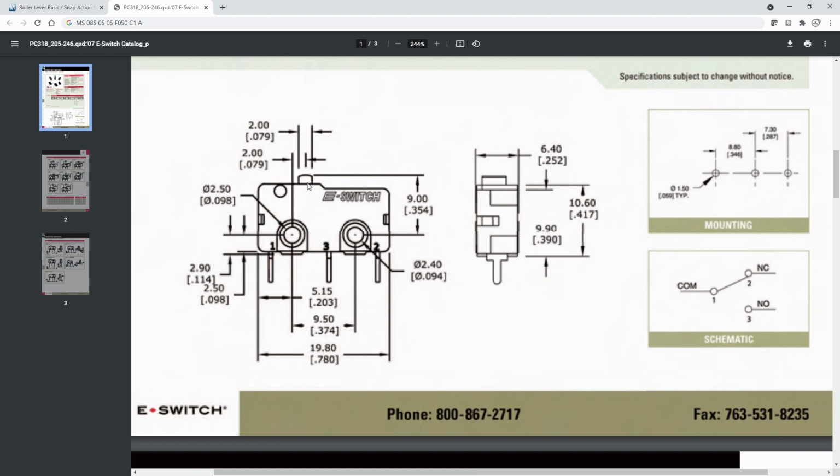So now, if you think about this, whenever you're connecting a switch that's controlling a light inside of a cabinet, when the cabinet is closed, it's going to be pressing this in. When it's pressing that in, it's disconnecting the normally closed, and that means the light's off. You definitely want your light connected to normally closed instead of normally open, which is kind of backwards from the way you'd usually hook up a switch. Because typically when you press a switch, you want to have something happen when you press it, not when you release it. But in our case, this is exactly what we want.